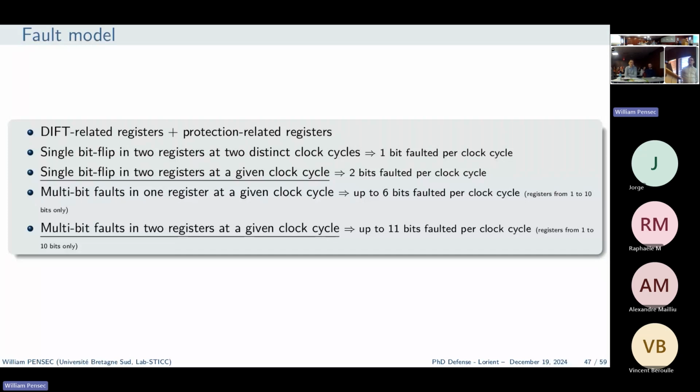Yes, I could protect the whole register file. It would be only 32 registers of 32 bits. So if I protect each register individually, it would be 32 registers of 6 bits approximately. So the overhead would be way higher than currently, sorry. But it would still be a good protection to protect even more the DFT and the circuit against possible fault injection attacks.